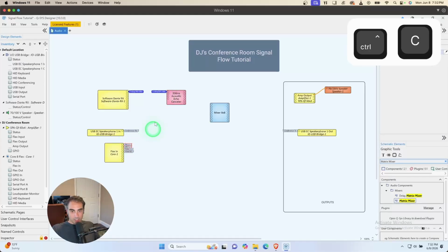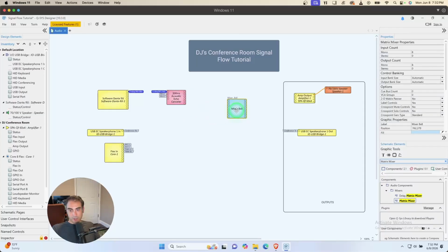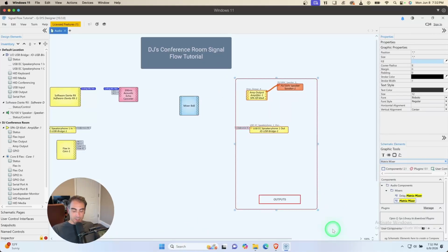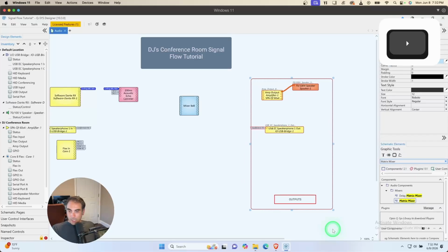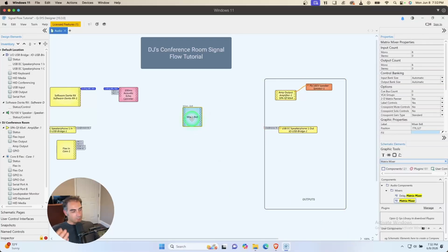You're going to need an AEC channel for every microphone in your system in the room. And now you can see what enabling reinforcement outputs did: it gave me separate outputs for my conference feed and separate outputs for the signal I'm going to be reinforcing through the speakers, which is very helpful when we are trying to keep things clean. Because if you don't do your referencing right, you're going to have all kinds of problems. You're going to have weird audio, what I like to call garbling. It sounds like underwater. You'll get all kinds of complaints. It's just not good.